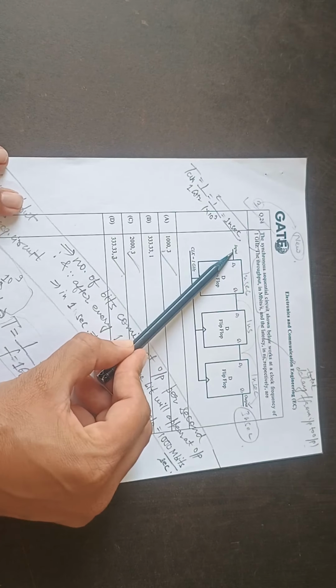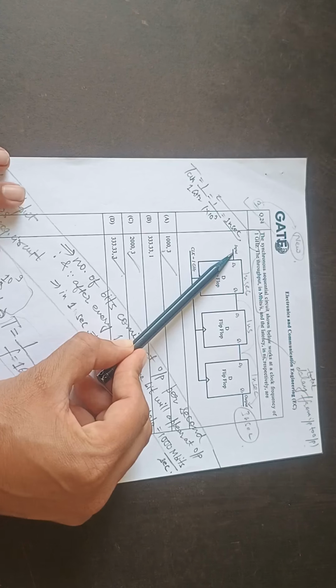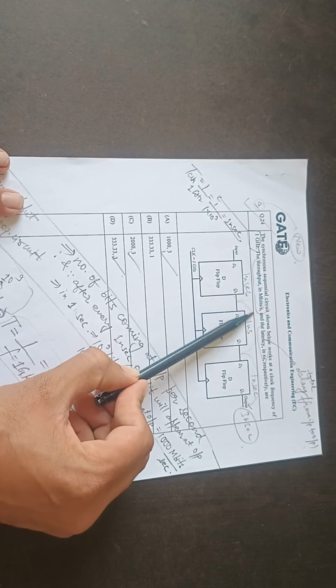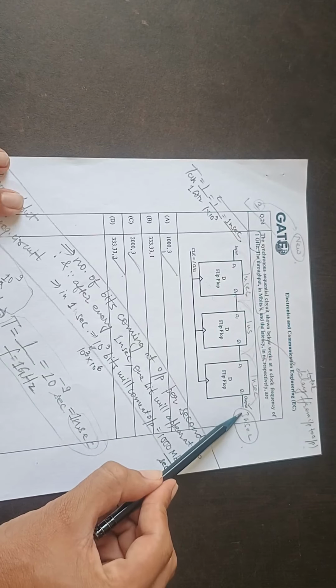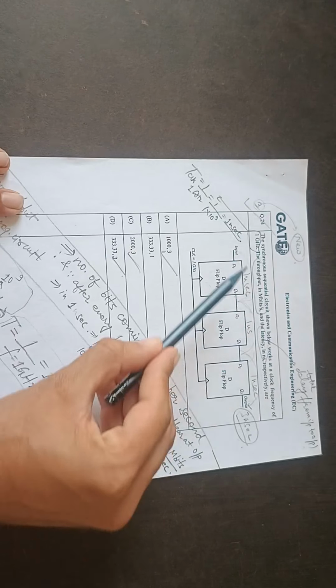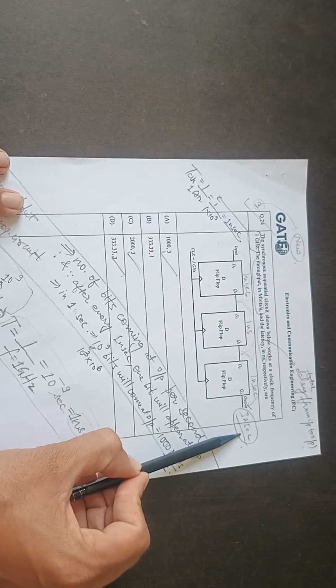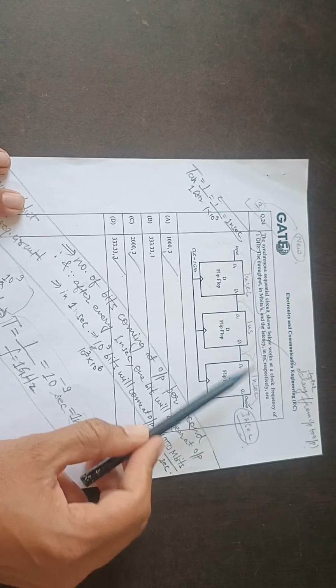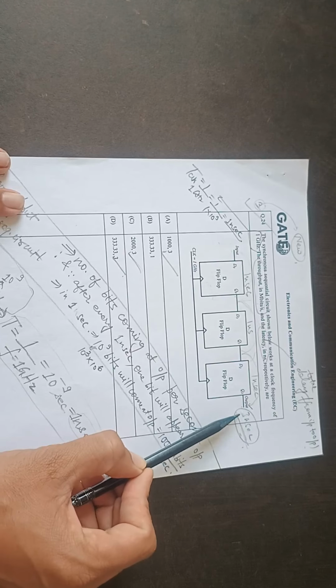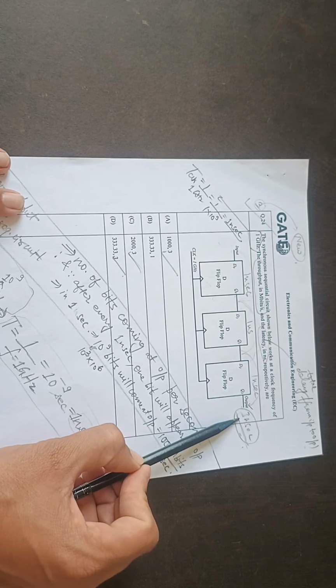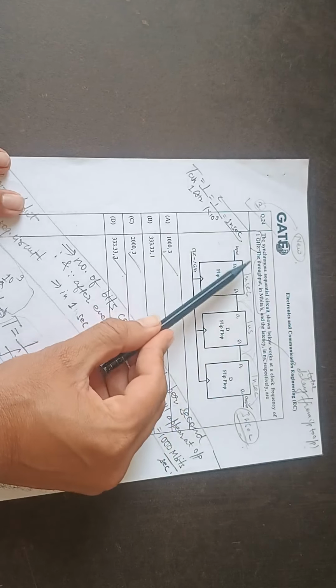So if your bit is here, then it will take like 1 nanosecond to come here, 1 nanosecond to come here, and 1 nanosecond to come here. So total each bit will take 3 nanoseconds to come from input to output. Okay, so it's a serial in serial out kind of circuit, a shift register. Okay, so this will be 3 nanosecond, and this new word is throughput.